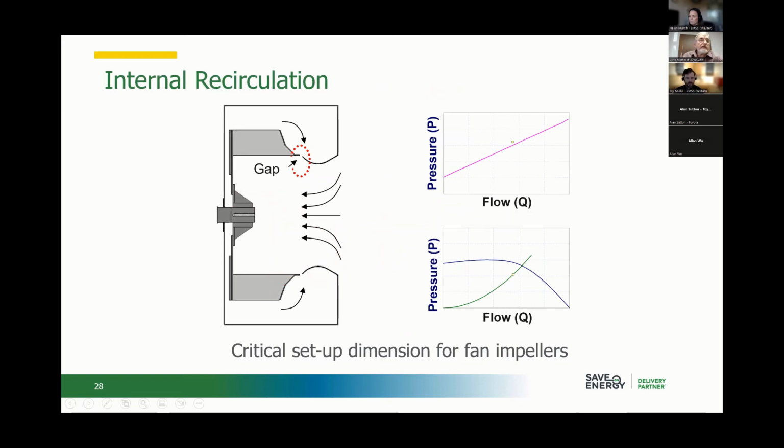Now, can I have that cone right here, Pankaj? Yeah. And let's maybe quickly touch on these so we can get to some of the questions, which I think touch on some of these issues as well. So this here is a fan that's degraded. I've talked about that. Now, this cone is not sized for this wheel. This cone's too big. Ideally, that cone should just fit right inside that wheel. This becomes the non-stationary part and this is the stationary, and as soon as that happens, you get a wee tiny bit of leakage.